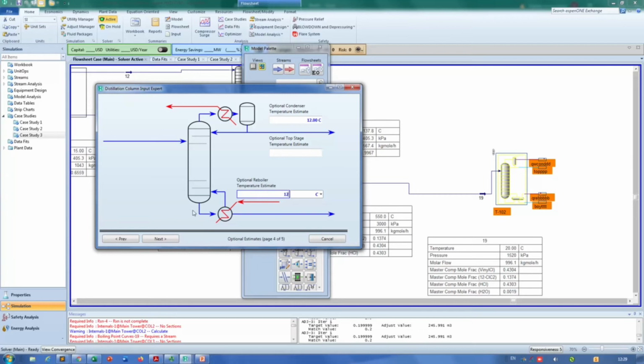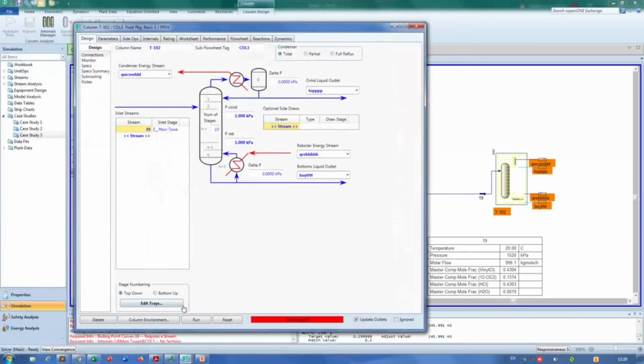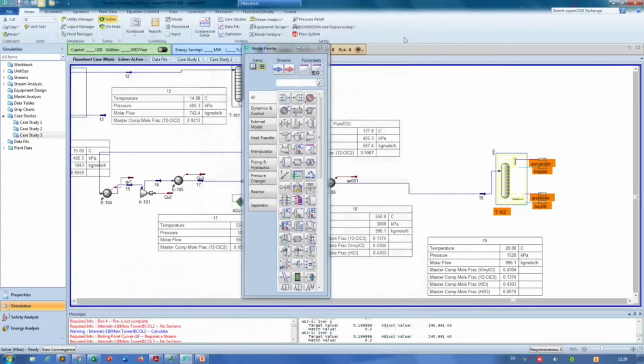Okay, so these are the things that we need. Next, the liquid rate, we don't have to worry about this. We can fix some reflux ratio, say 3, 1.75 and so on. Okay, and then press done. Obviously there are a few other things that we need to do. So what I'm going to do is close this. Okay, I will close this.